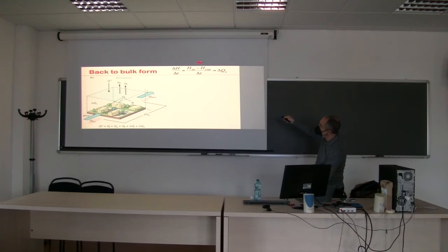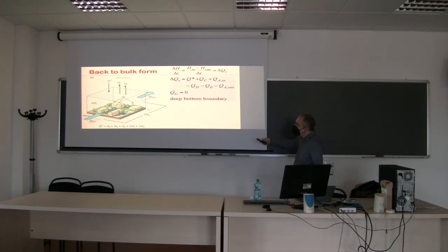And we still can write something that looks like this energy budget, where we are interested in the change of the thermal energy content of this control volume over some time, so a change in the power, if you want. Now, what you would notice here is that when the interface was very thin, the mass was 0, we said the storage, basically this term goes to 0 because M goes to 0. But this is only for a thin interface. When you consider a big volume that has houses and trees and cars, obviously this is a system with a large mass. So the change in the heat content is no longer negligible. And now you should keep this change in the heat content.